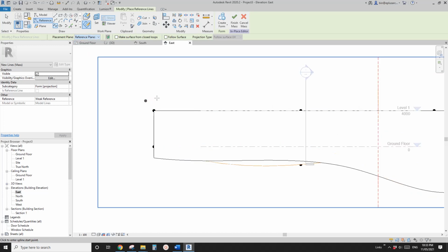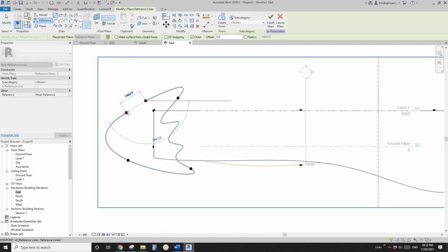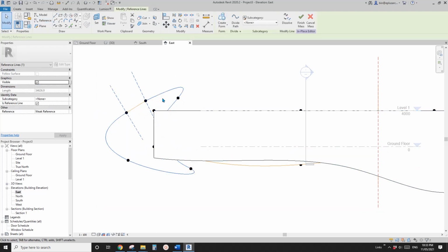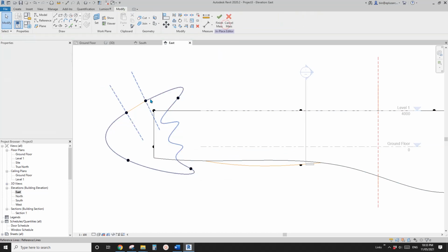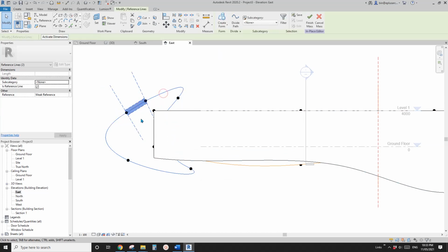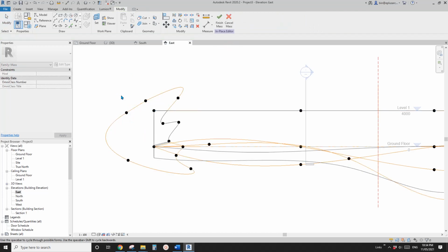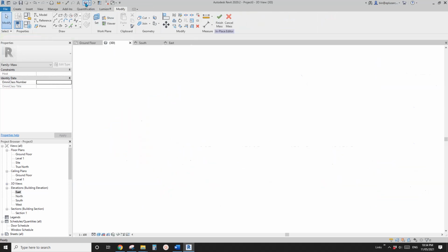So now we can do it this way. Okay, no problems. And then finish, close it, because you can't close a spline. And then you can just create a void. So sorry, select both the spline and this straight line, and create a void. And where's the option? That's the only option. That's fine. Let's go to 3D views.